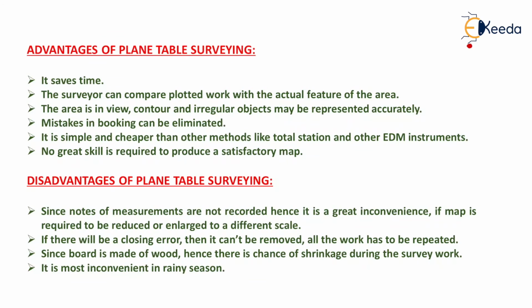Now the advantages of plane table surveying. First, it saves time because we don't need to record readings in plane table surveying, and there is very little office work, so it saves time. The surveyor can compare plotted work with the actual features of the area. It means that the whole area is under the vision of the surveyor, so he can compare the plotted work with the actual features of the area.